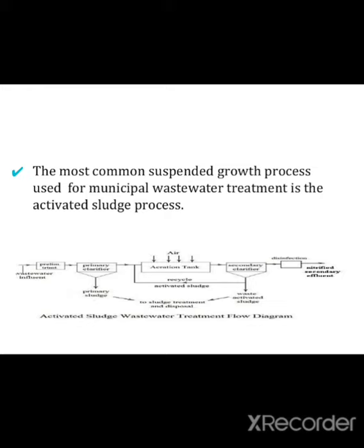The water gets aerated. We know BOD, biological oxygen demand. Here the biological oxygen demand gets reduced, because we are supplying the oxygen, so the demand gets reduced. The aerated wastewater is supplied to the secondary clarifier as a secondary treatment. Here, same as in the primary clarifier, the sludge is settled down into the recycle process.